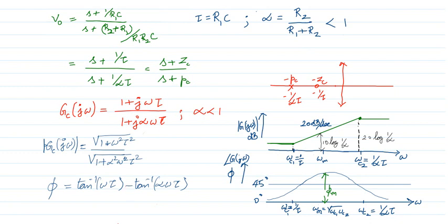Now you observe very closely. I have explained in a separate video how to plot a Bode plot, and you can look at that video for additional information. But here I briefly explain what we are going to do. In a Bode plot, whenever the numerator is working, it will contribute plus 20 dB per decade. Whenever the denominator is functioning, it will contribute minus 20 dB per decade. This all happens after the corner frequency.